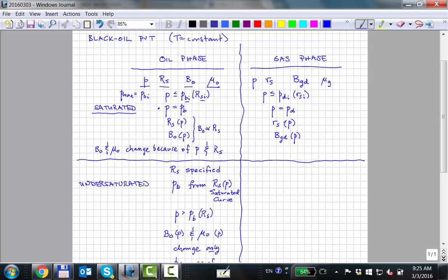So sometimes we'll create this table to have saturation conditions, bubble points and dew points, that are higher than what we think is the initial highest in reality. Basically this is our max saturation pressure. So the point is that in that saturated table, the one thing you know for sure is that the pressure given in the table is the bubble point of that oil. That you know for sure. That's guaranteed.